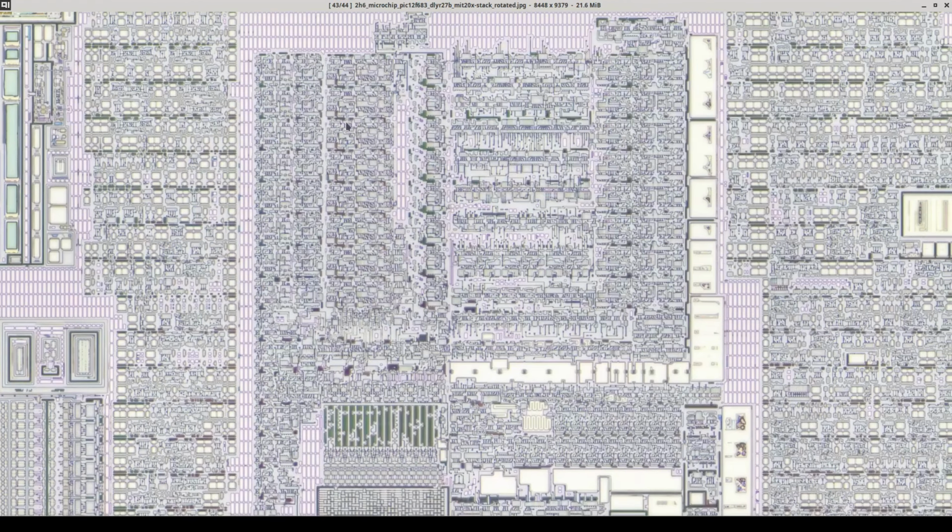From my recollection, the high bits of the instruction word are a kind of global mode selector that specifies a couple of different instruction formats, and so they might be beginning to pre-decode the instruction in the MSB as soon as it's latched. Then going up a little bit, this region here has 8-way symmetry. The processor has an 8-bit data path, and so this is probably the accumulator and main register path, and then probably additional ALU components. Down here is likely instruction sequencing.